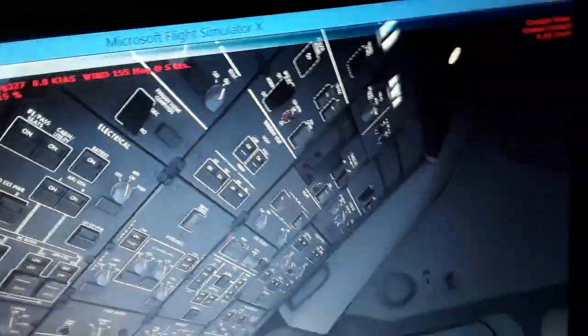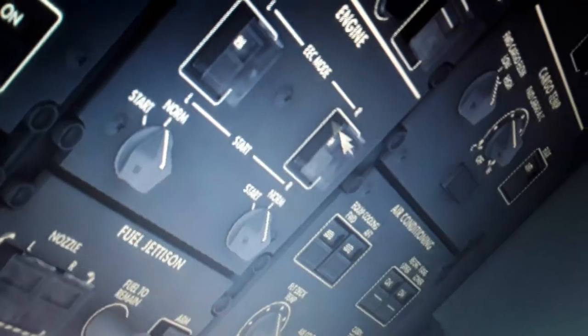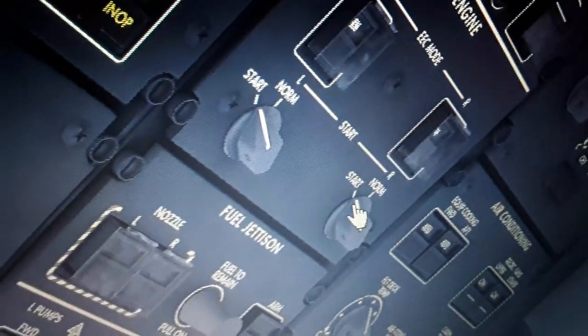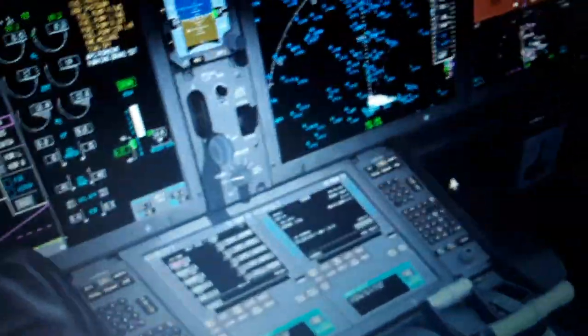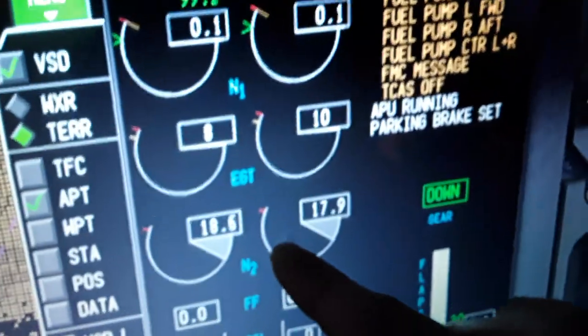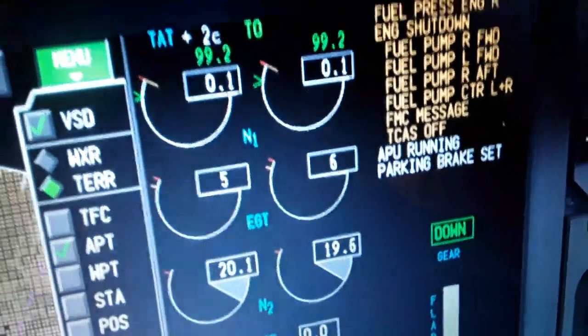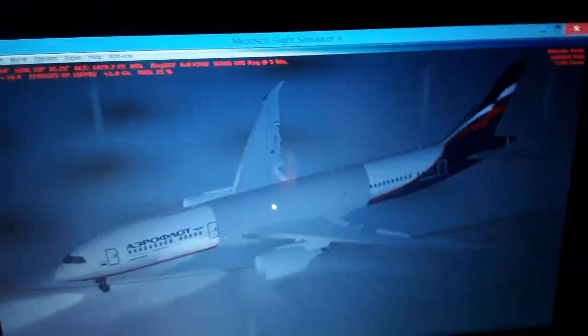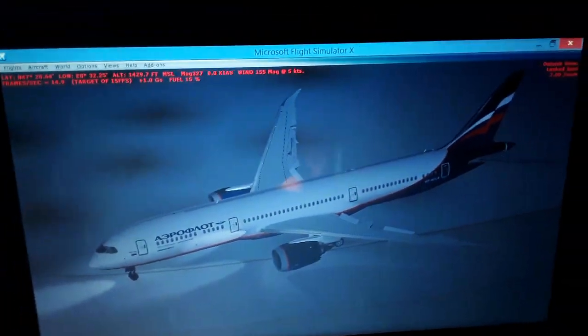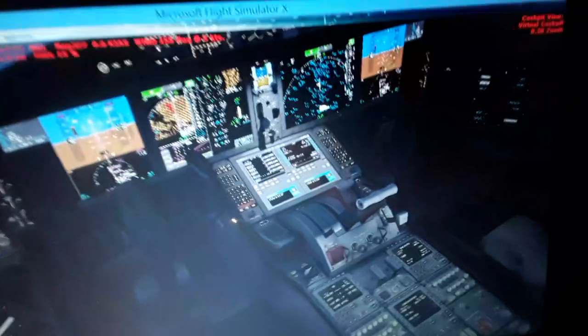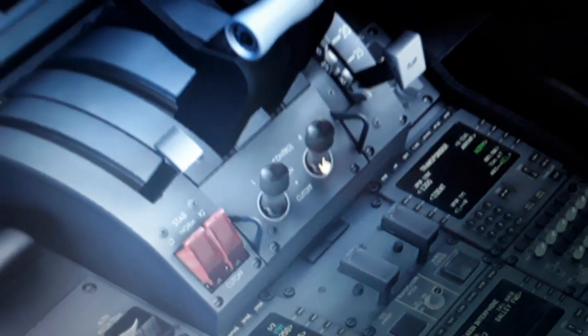So we're gonna reset very quickly. We go in the overhead panel and restart the engines. Both engines in auto start. You see the reconfiguration of the switches in the overhead panel with amber color lights. So we have now pressurization inside, the N2 stage above 18%, 19%, 20%. So now we can let the fuel flow. You can see we have only pressurization right now into the engines, air from the APU is admitted. So we let the fuel control on. Both fuel flow valves open.